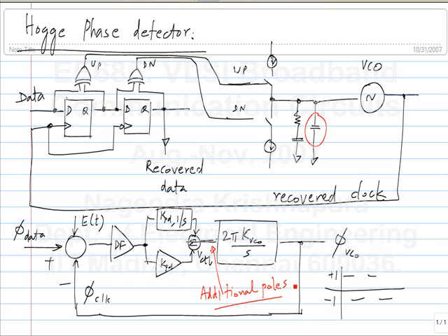And how do you make this phase detector? I think you already have all the circuit design experience to make this. You have made the flip-flops in the first assignment and you also know how to make the XOR gate. Again, you can all choose any architecture, but here we have been talking about high-speed equalizers. In that case you will use CML circuits for the XOR gates as well as the latches. But of course it will work even if you don't use CML. I mean, you realize this logic using any other type of realization, it will work. Okay.